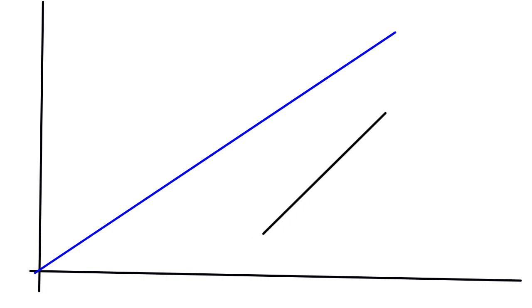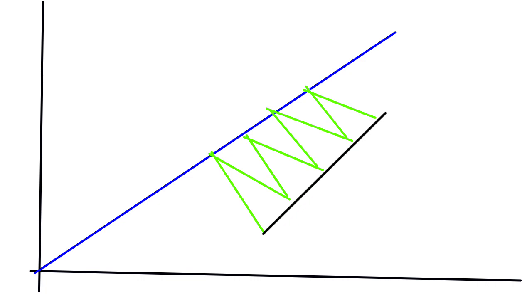That's why the lower point should be y1 and x1, and the upper point will be y2 and x2. That's easy. And now there will be mass transfer between the operating line and the equilibrium line, and you can draw the stages like these, and it's same like absorption but just reverse of it.